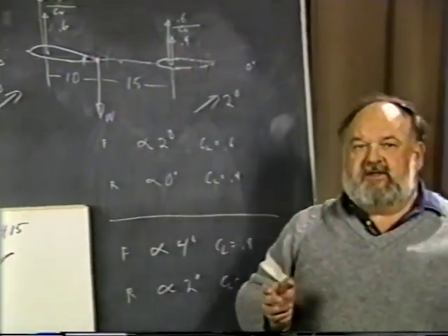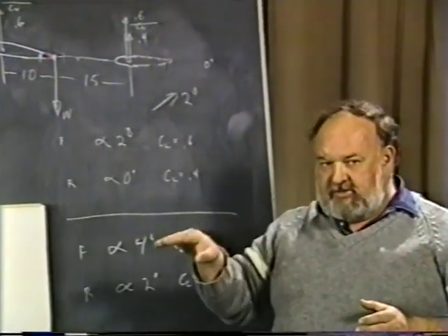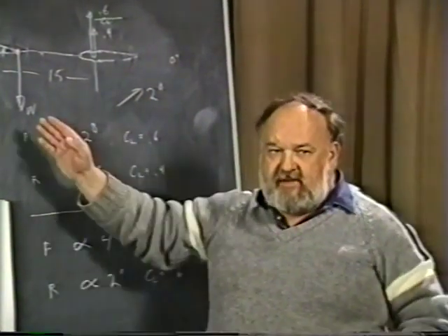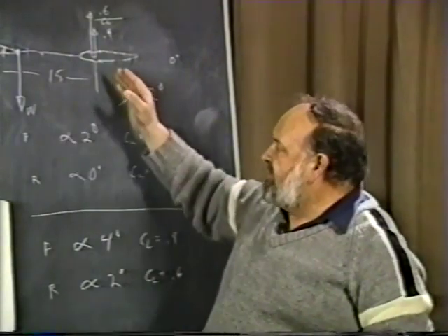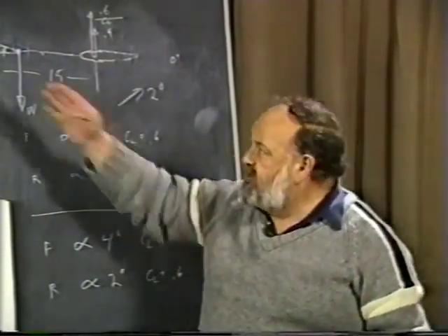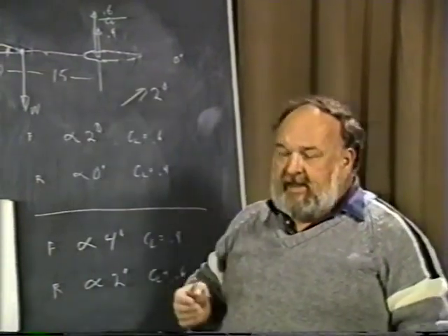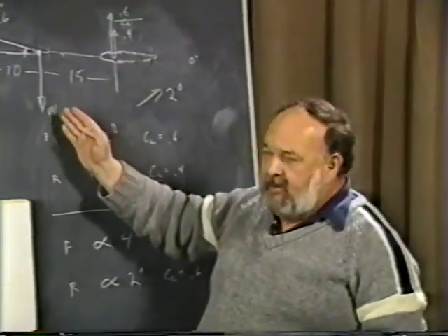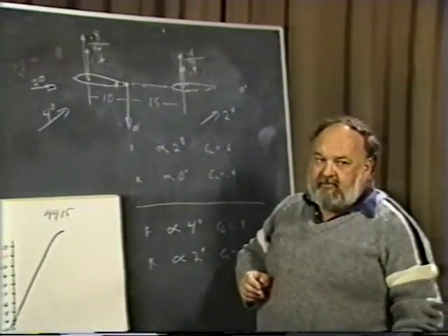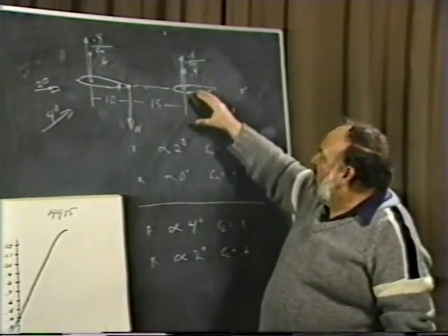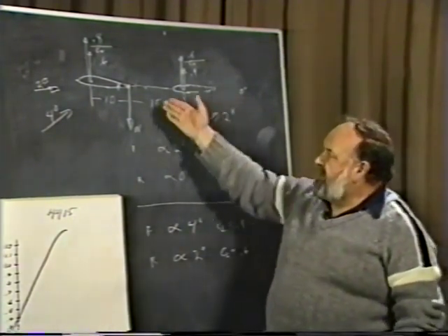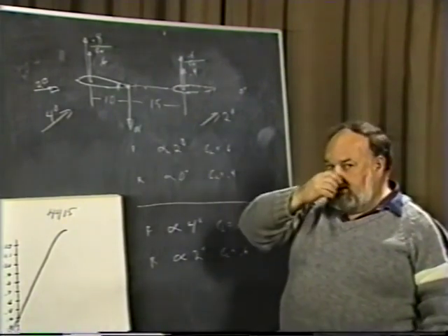This condition is somewhat sensitive for longitudinal stability, because as we change the center of gravity, you can see what effect this has on the loading on the tail. If we go back to this example again, where these two surfaces were identical, and for whatever reason we had to move the center of gravity further forward, then immediately, to keep the airplane in balance, we would have to reduce the incidence of this. We'd have to let that same size wing lift less than it does.